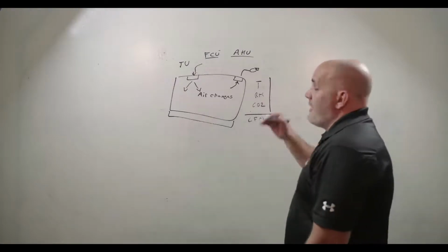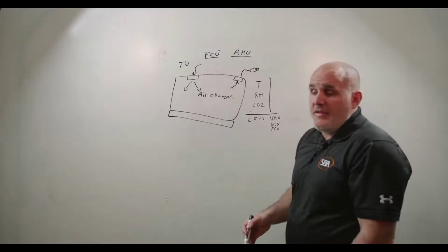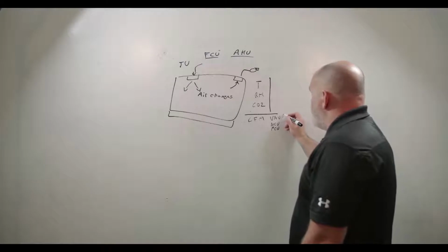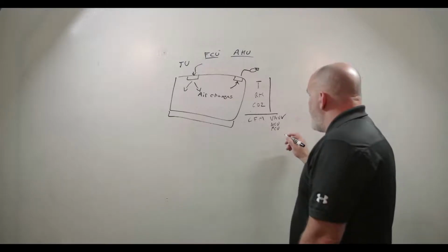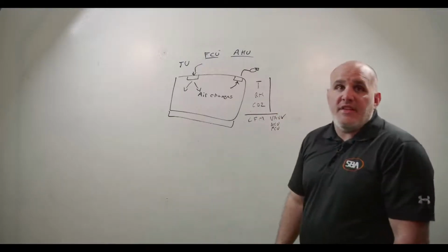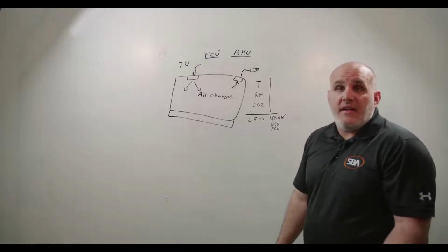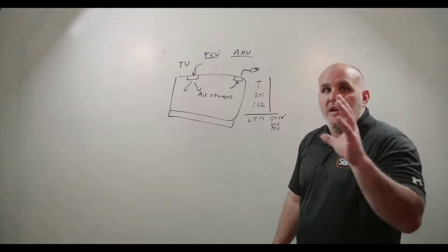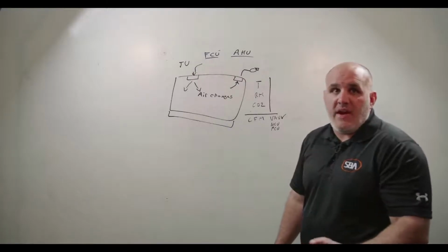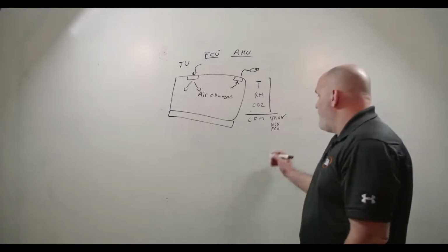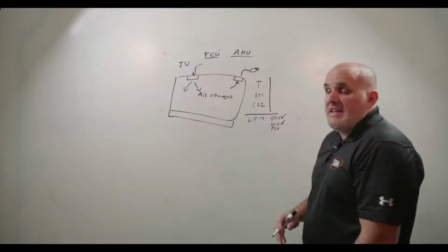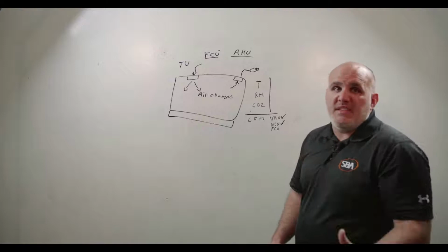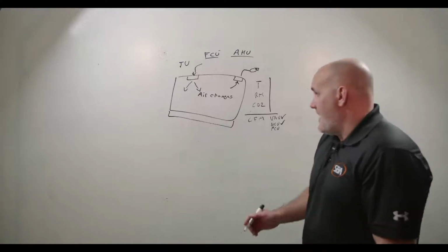And then you're going to have airflow potentially regulated at the air handler, depending if it's constant volume or variable volume. Now, so that's the VAV, right? At the air handler, if we're directly dumping air in there, we'll either vary the fan speed or the fan frequency to modulate airflow, or we'll just do a direct constant volume airflow. And with fan coils, we will typically have a low, medium, or high speed that will be set by the balancer along with some balancing dampers.